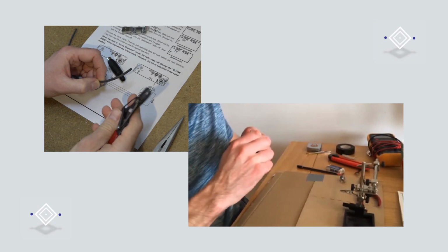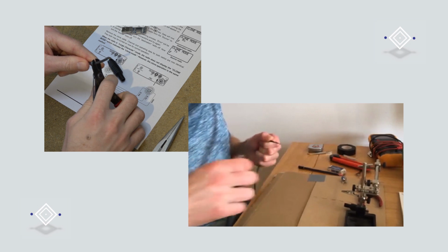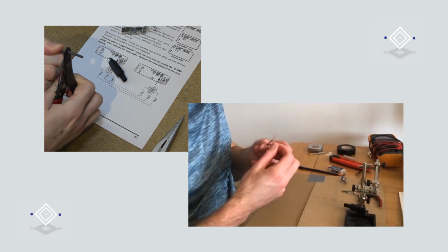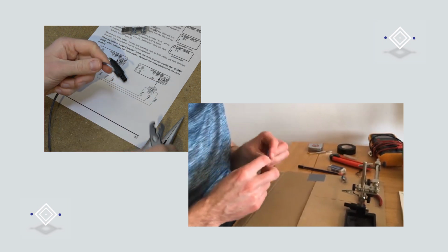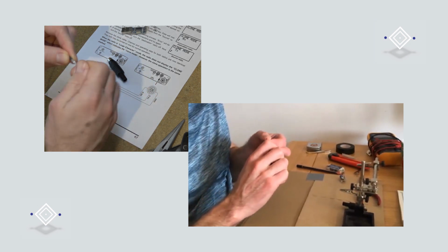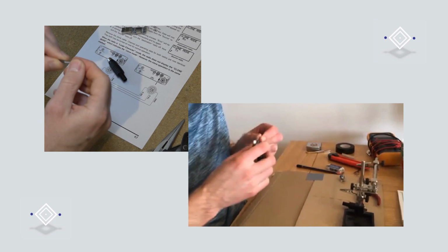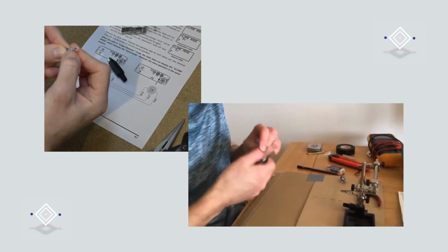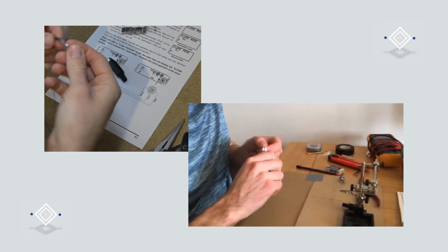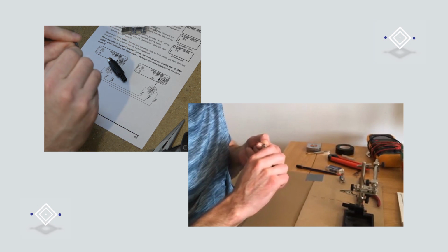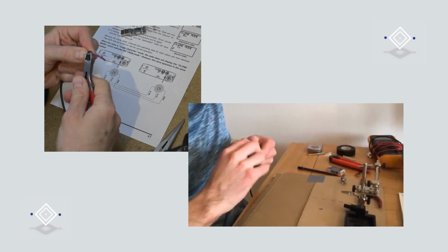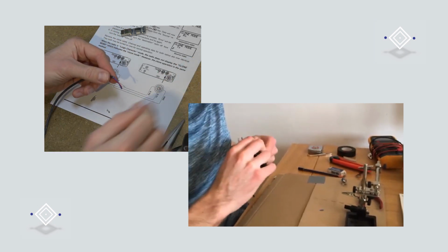Cool. So you just want to strip maybe about 1 inch of the outer jacket off with some wire strippers or a knife. And on this wire that we're using, it's got a sort of foil screen. You can just get rid of that, tear that off, and there'll be a separate actual screen wire. You might need to just use a knife to help get rid of that, or some cutters. And you can do that at both ends.